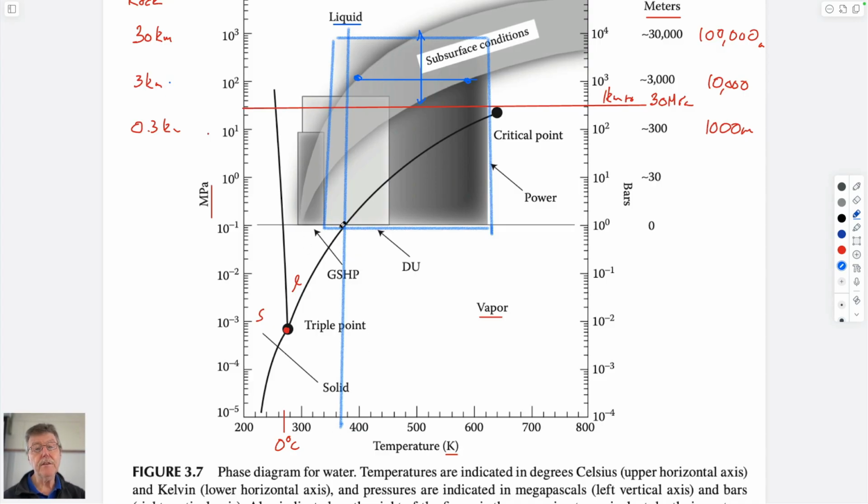It exists slightly below that because you can actually use what's called a binary system. So you have water that comes out at 120. You flash it to steam, it ends up being at 100 degrees centigrade or less. And then you use that to transfer the heat to a different fluid, say isopropanol, which boils at 40 degrees centigrade. The heat's transferred to that in a closed system. It boils the isopropanol, that runs through a turbine in a closed system. It's collected, condensed, and then turned back to liquid again.